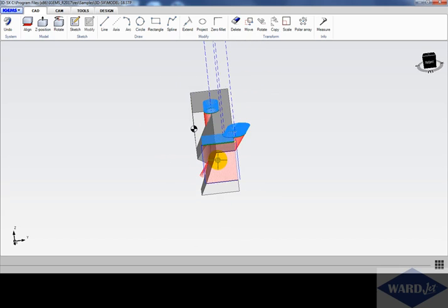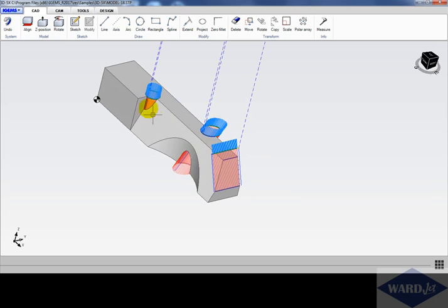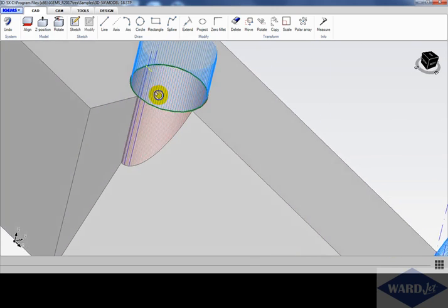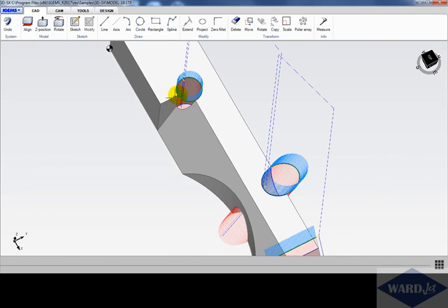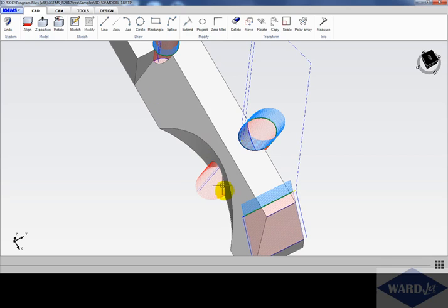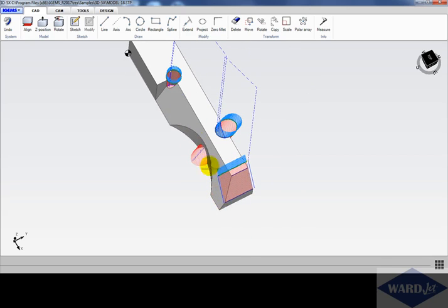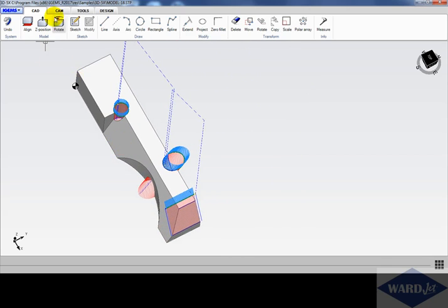All right, so then for this cut here, we're basically going to have to program or draw in a little line to go from the end point of here to the center point of this circle, and then over to this point here, so we can pick up off of that edge to be able to program this bevel cut, fixed bevel cut along this edge here.